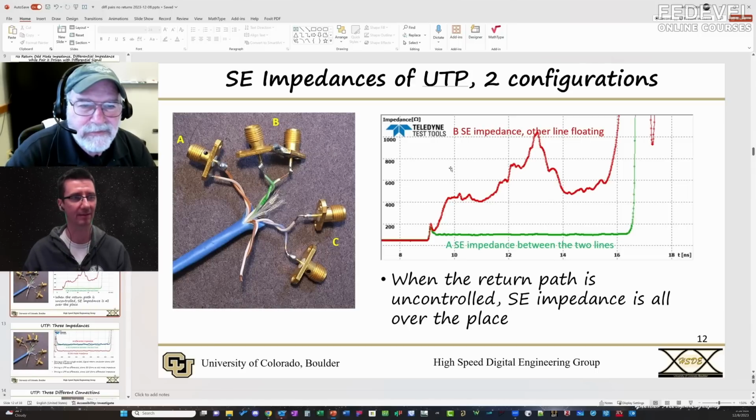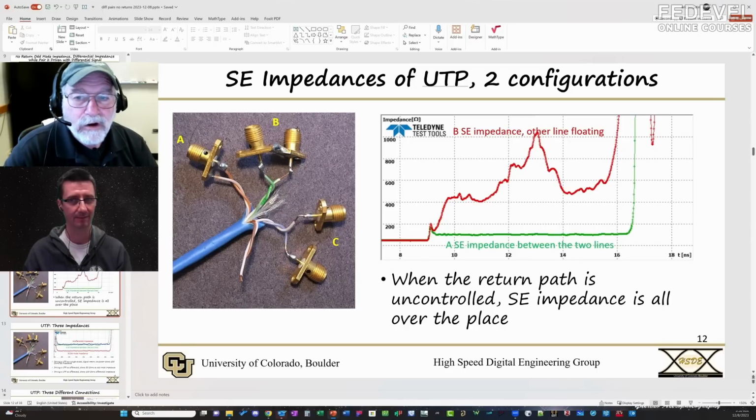C will be very similar. Yes, right. Looking at this one as a single-ended impedance, it'll be identical, because they're close together. His return is going to be exactly the same as his return. So this line, single-ended, and this line, single-ended, they'll be identical.